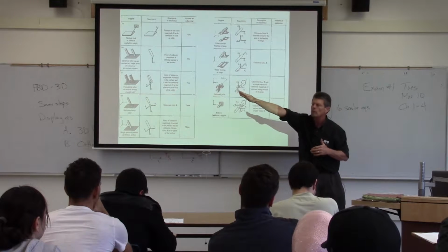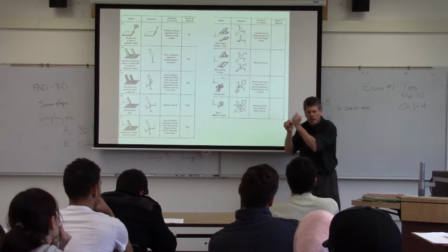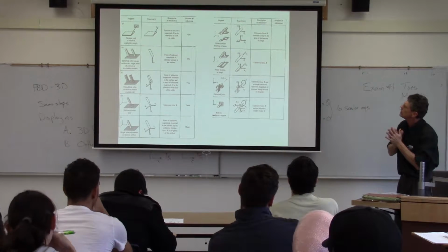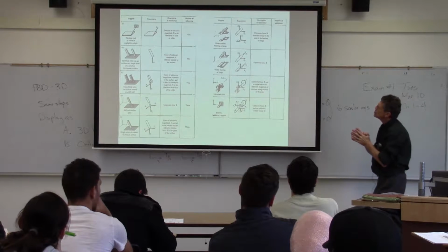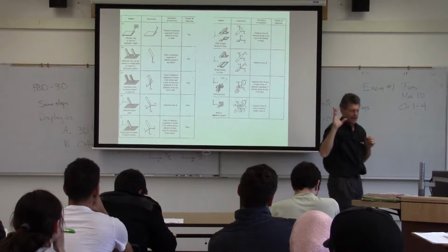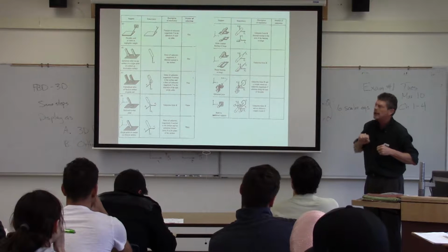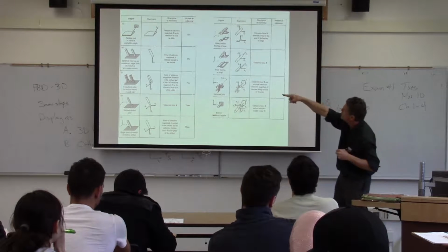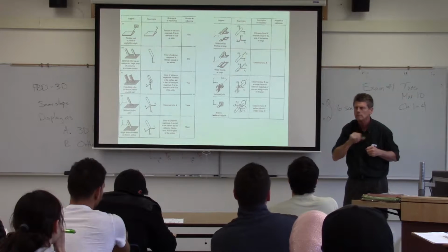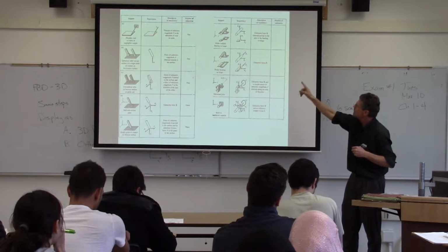Especially if you think of that rod going out for any sort of length, there's really not enough moment capacity there. You have to create a couple to resist a moment at the end, and there just isn't a whole lot of room to create that. So generally what you'll see in your homework problems is this, and that's why I wanted to bring that out. In terms of the length of that axis or pipe, there isn't anything resisting that, so it could slide along freely if it's a bearing or just a hinge.